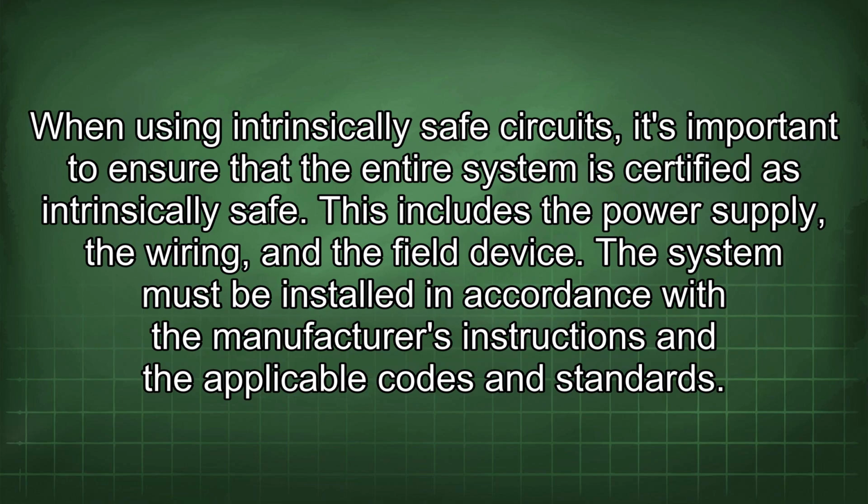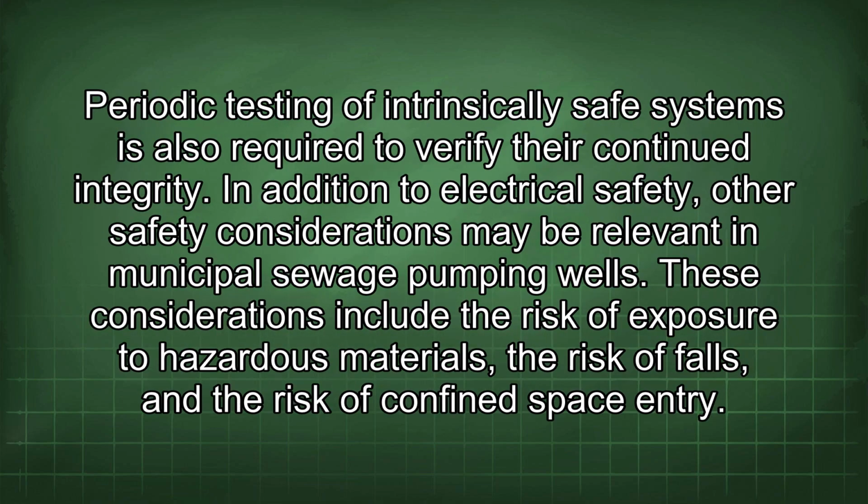When using intrinsically safe circuits, it's important to ensure that the entire system is certified as intrinsically safe. This includes the power supply, the wiring, and the field device. The system must be installed in accordance with the manufacturer's instructions and the applicable codes and standards. Periodic testing of intrinsically safe systems is also required to verify their continued integrity.